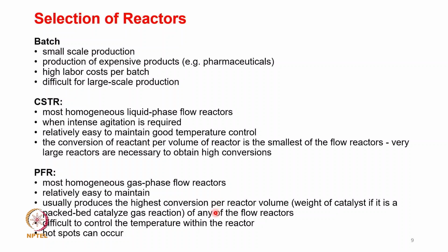The difficulty is that there is no agitation or well mixing happening in the PFR, as the reaction happens when a front moves from inlet to the outlet. So as a result, the temperature control within the reactor is not easy. There is no means by which you will be able to do good temperature control. As a result, hot spots can occur inside the reactor.